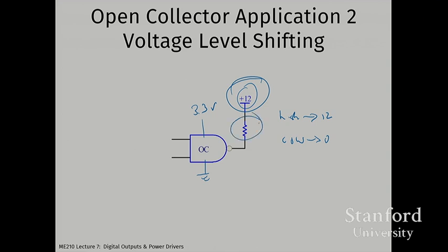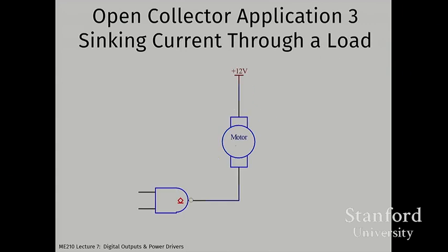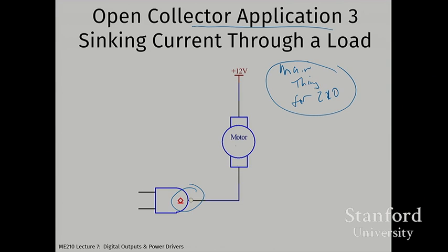And as we've talked about several times already, you need to be picking that resistor so that it works in the high and the low state. And that's math that you've heard about several times and can do by now, we hope. The thing we're always going to be doing, this is application number 3 on this list, this is the main thing for this class, for ME210. We're going to be using the outputs of open collectors with plus VS and ground to basically turn logical input information into a control voltage that can turn motors on or off.